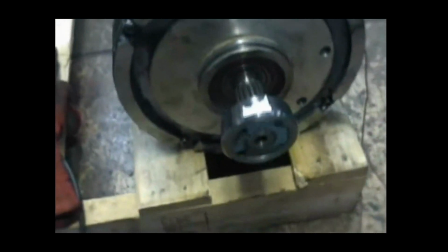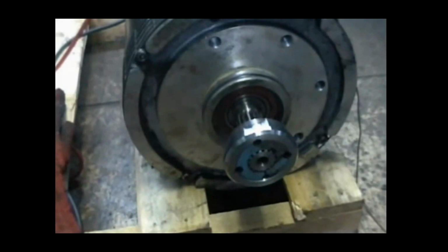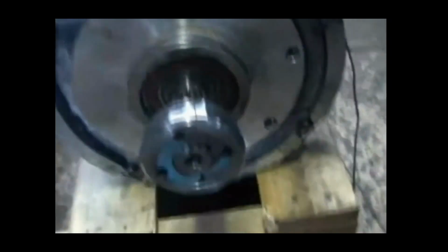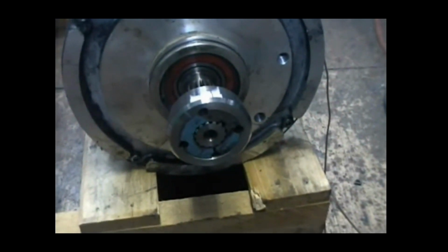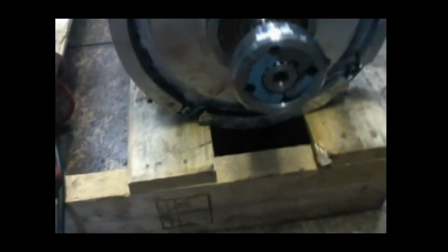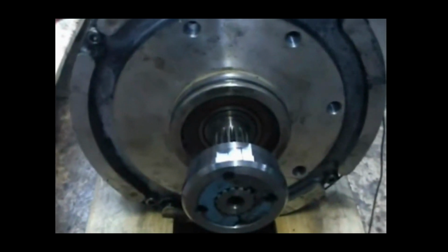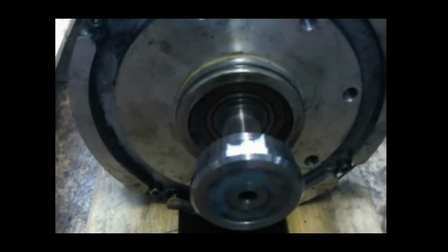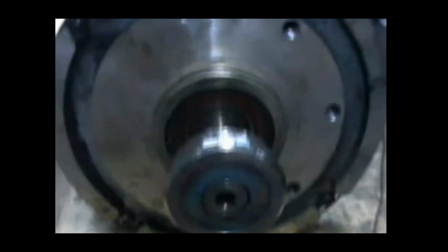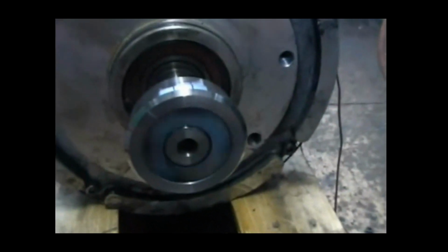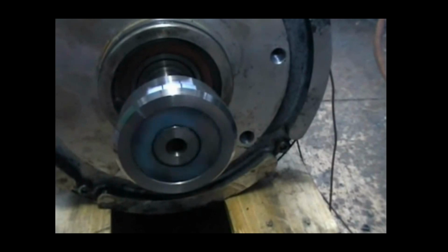Now, the next thing that we're going to do here is I'm going to start back up again, and I'm going to apply 36 volts DC to the shunt field via our gel batteries here. Okay, I'm trying to do this single-handedly here now. So I'm going to connect the series power back up again, the 12-volt car battery. Now we're spinning away. So now I want to observe the shaft speed as I connect the 36 volt DC shunt field.